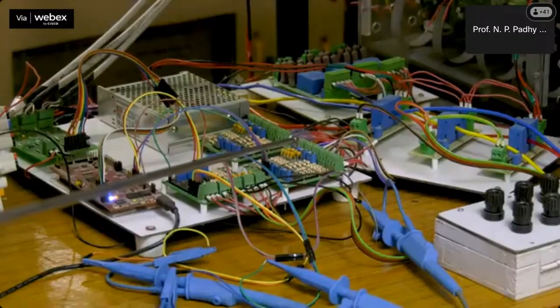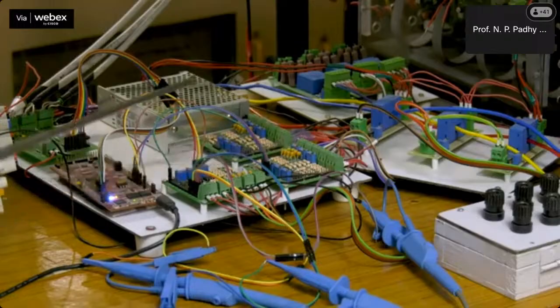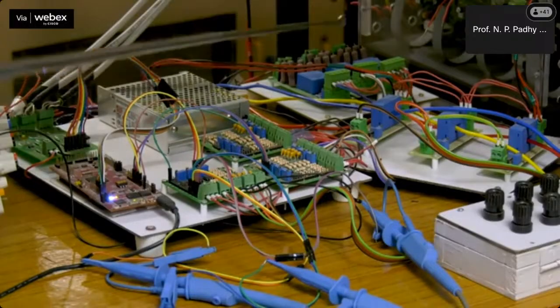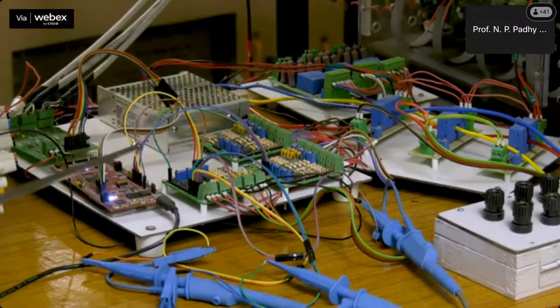To avoid such situations, the output of the sensor is given to biasing circuits, which bias the input signal above 0 level, and the biased signal is given to the ADC pins of the DSP controller. These ADC pins convert the input analog signal into a 12-bit discrete signal. The control system requires 3 voltage, 3 current and DC voltage signals as input and generates the required PWM pulses to control the grid tied DC microgrid inverter.